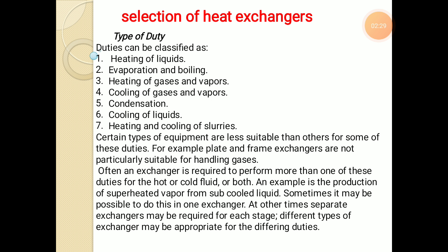So as I said earlier, the selection of a heat exchanger depends on many factors. The first factor is the type of duty or heat exchange rate. This type of duty can be classified as heating of liquids, evaporation and boiling, heating of gases and vapors, cooling of gases and vapors, condensation, cooling of liquids, and heating and cooling of slurry.